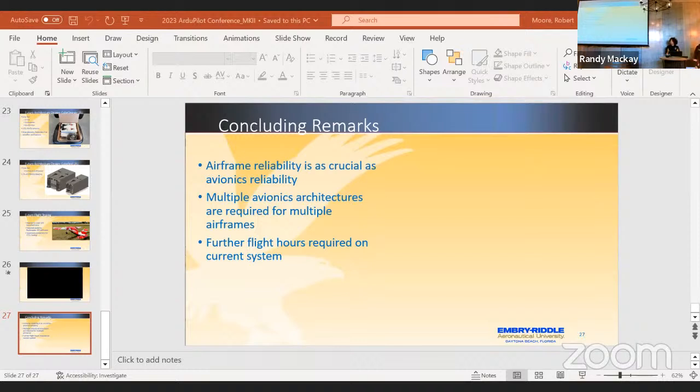Because those are all kept small, the autopilot starts fighting that offset from the moment you switch to it and builds up from there, rather than having a massive built-up integrator that it can't do anything with. So all that internal state is handled inside.